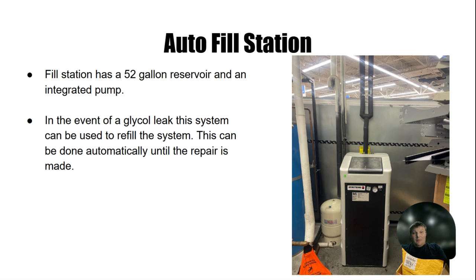It's regulated by a pressure switch set to the pump suction operating pressure, and a float switch in the bottom of the pump that prevents damage to the pump in this fill station. These, as far as I can tell, are going away and not going to be installed anymore.